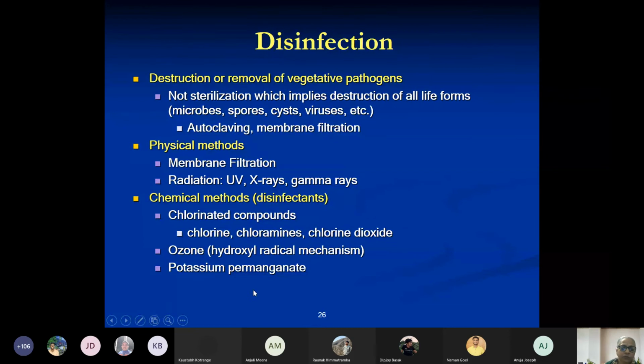So those of you who are from villages, you know that if you add potassium permanganate when you suspect that the microbial concentration is high, that is quite effective in controlling microbes, but it gives a pinkish, pinkish purple color to water, and that is what people don't like. But in emergencies, most people recommend the use of potassium permanganate because it's non-toxic.